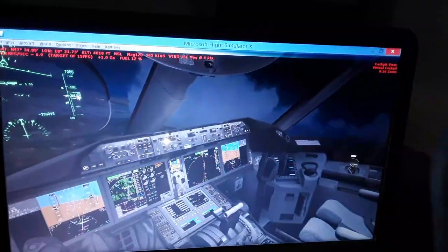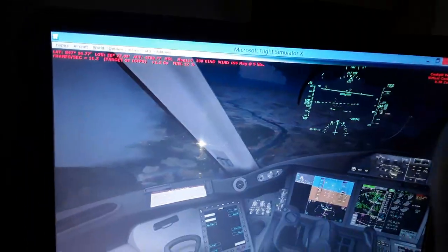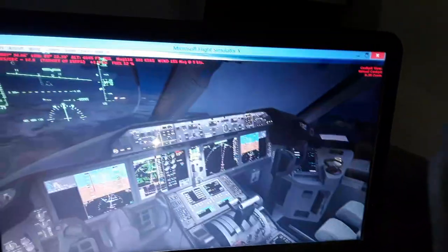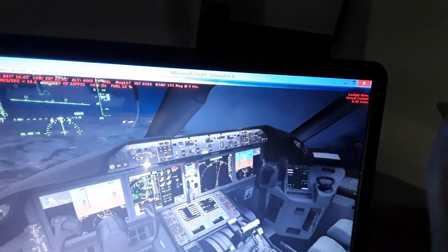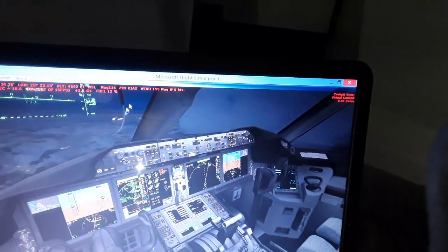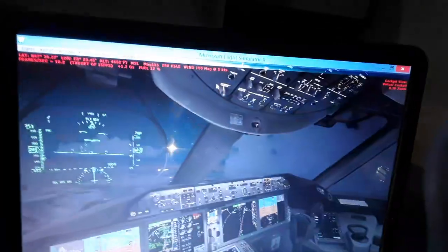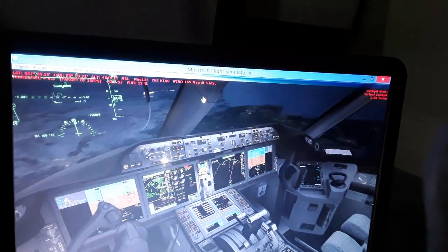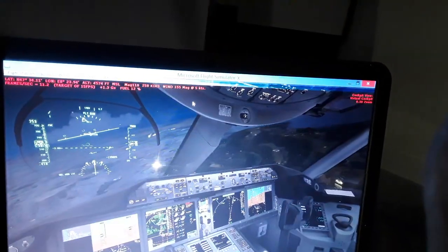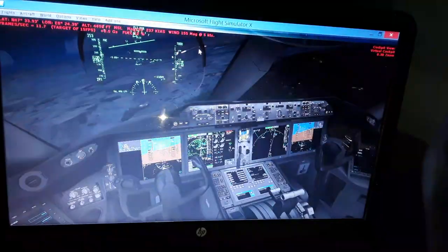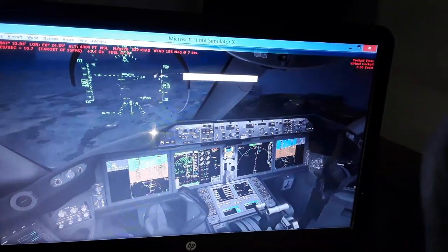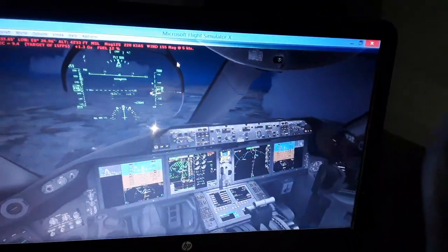Landing gear down. So you can see we're very close for the landing. Also flaps. Use a bit more flaps. A little bit more descent rate, and we need to align over here with the runway. Use right rudder, like now, right rudder pedal for this alignment. So we have the center line at some airspeed right now. We have 4 more minutes for approach and landing, like this.